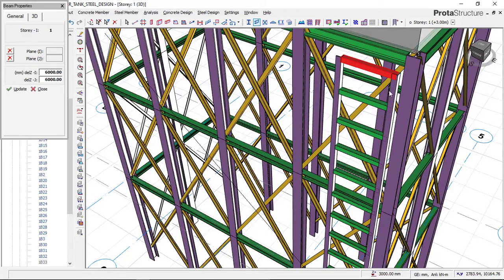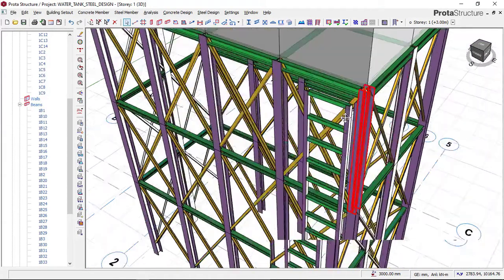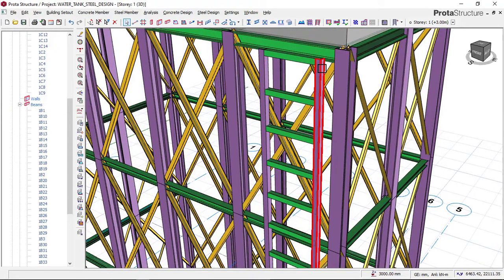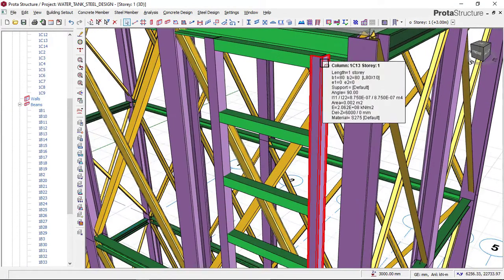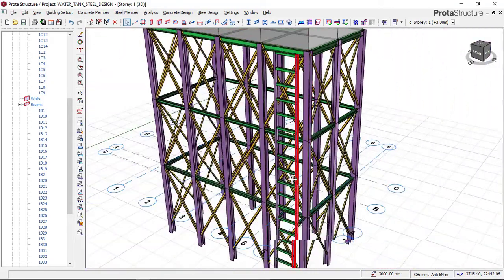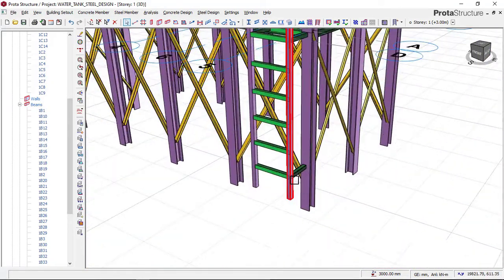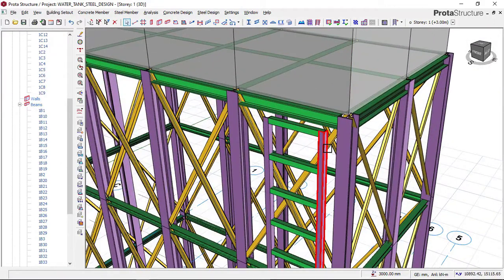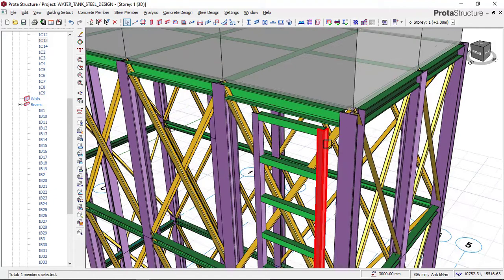Now click on escape. Now this is not okay because there should be an extension between this end of this staircase column and this riser. Just as we have an extension of 500 here from this down to this, the same thing we will have here. So we will have to edit the length of this staircase column.